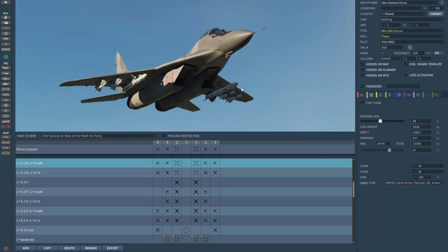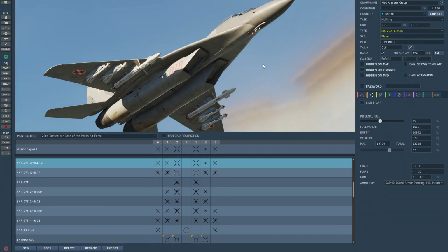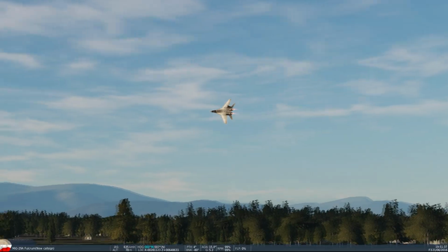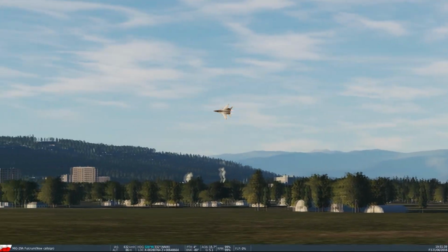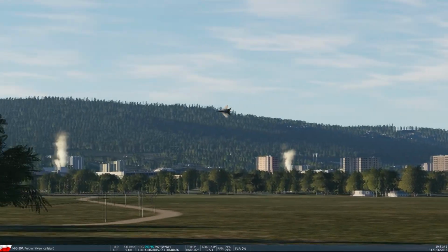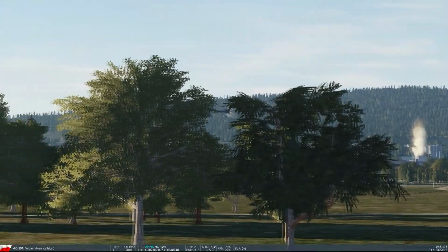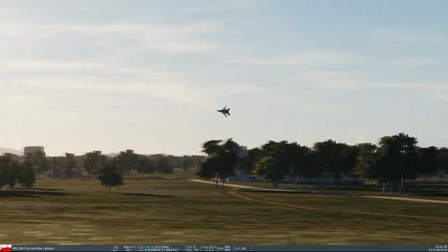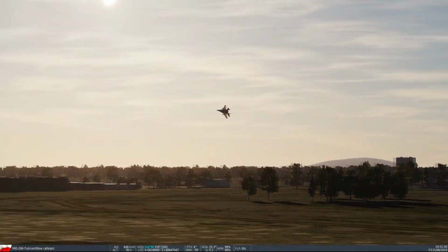Measuring the limiting sustained turn rate manually is not a trivial exercise. It demands a high degree of skill. At the very least, a quarter circle flown with a steady altitude, constant speed, zero vertical velocity, and stable G-loading. Not an easy task. So, I've decided not to gamble.